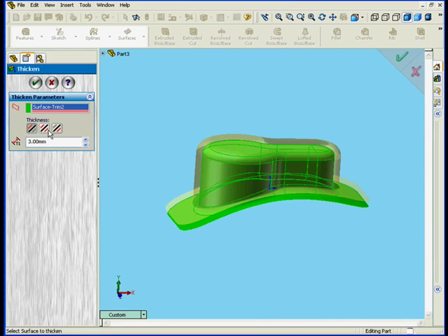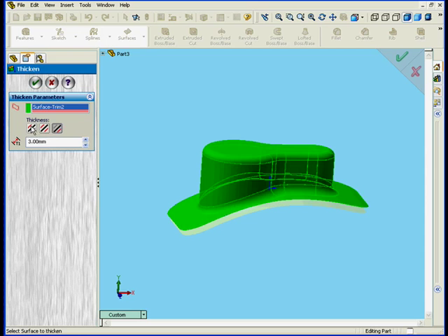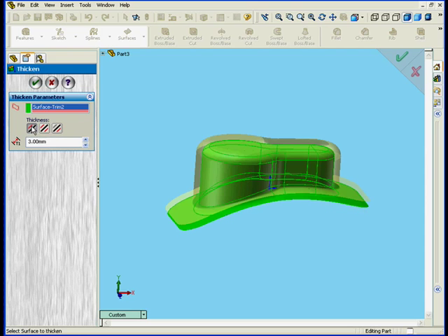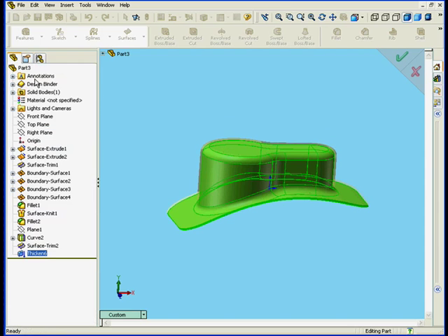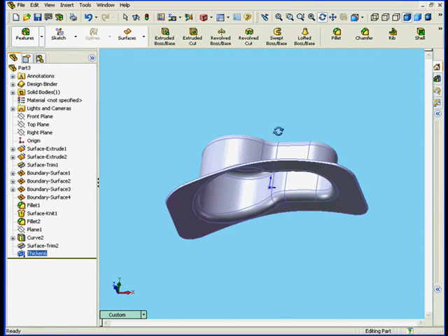Next, our control area gives 3 thickness options. We can thicken side 1, we can thicken both sides, or we can thicken side 2. I'm going to select Thicken side 1. Let's enter a 1 millimeter value. Hit the Tab key and click OK. And here is our solid.